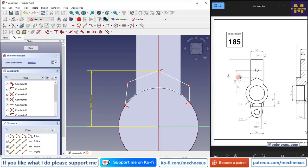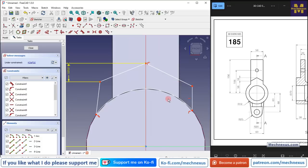Now I will define the vertical height of 16. So select it and define the height 16, and here I will select this point, and we will add the horizontal constraint. So here it took the vertical.